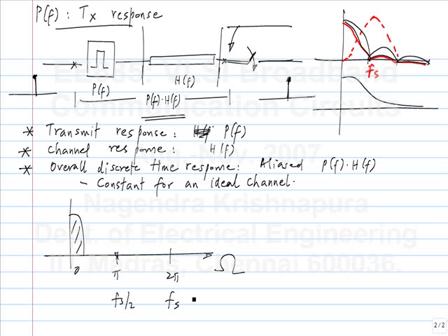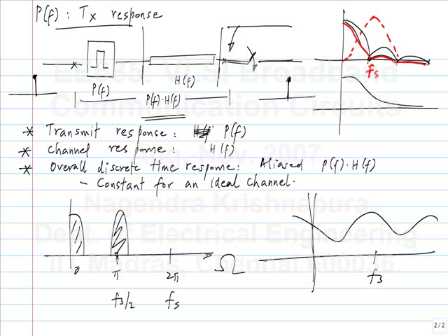If you have plus 1, minus 1, plus 1, minus 1, it has a frequency of pi radians per sample, or half if you remove the radian. And this is a high frequency. So if you have a discrete time frequency response which is like this, where this is Fs, this is a low pass channel. This is also low frequency, the same as DC. But this whole part is redundant. You can only look at this and judge whether it is high pass or low pass.